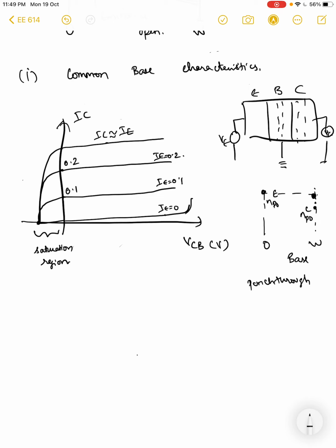And avalanche breakdown, we know, happens at reverse bias because of the potential difference over the distance at which the carriers are accelerated, right? So basically that will lead to enhanced carrier velocities, leading to impact ionization of further carriers and so forth, right, leading to avalanche currents.